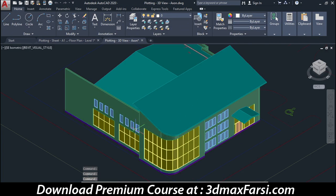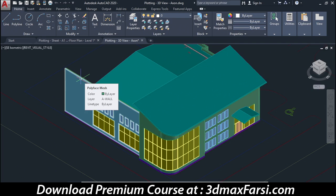However, I do want to stress once again that if I zoom in here and select some of these items, all of the individual faces of what used to be walls are now just simple polyface meshes. So when you export over, it will do its best job to create geometry that matches the size and physical location of the geometry that was exported. But since AutoCAD doesn't have objects like we do in Revit, it's going to interpret it in the best appropriate objects that it can on the AutoCAD side.